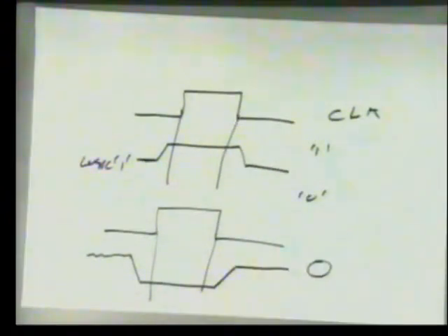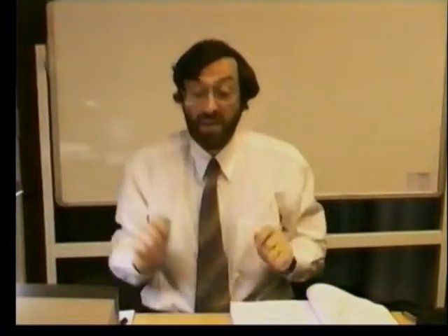Those are the rules. While the clock is high, the data line must be stable for the whole of that clock period, all of it. If you want to change the data, you take the clock line low, and then you can fiddle around with the data line. It's outputting a 0 or 1, but then it must stabilize, and then you take the clock high and hold it high while the other end reads it in. Those are the rules. 2 bits as logic level 0 and a logic level 1.